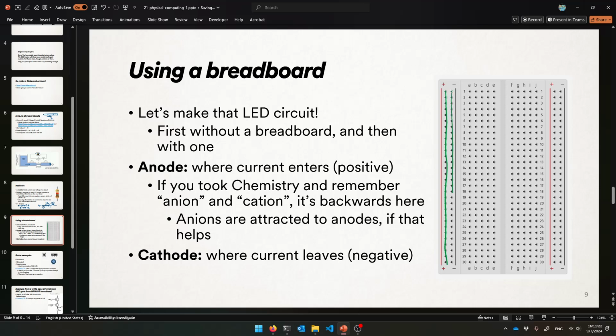So if you bring the positive end of your battery into the plus side, just any of the holes, then this whole rail is powered. Does that make sense? And you do the same thing with the negative end of your battery on the negative side. And if you want to do the same on this rail, because you know how they're going to be connected, you can connect this guy to this guy, now you've got power flowing on this side, positive. Same with the negative. Well, you can do that too, okay?